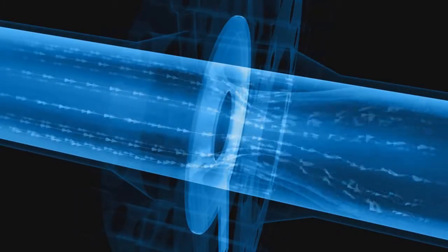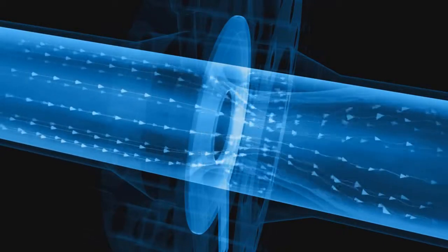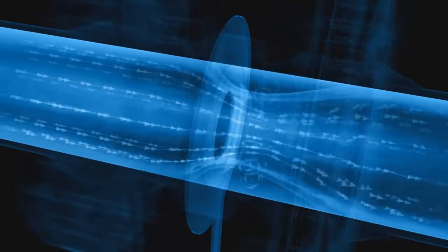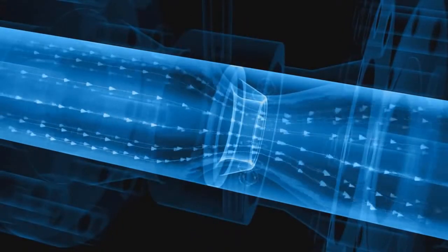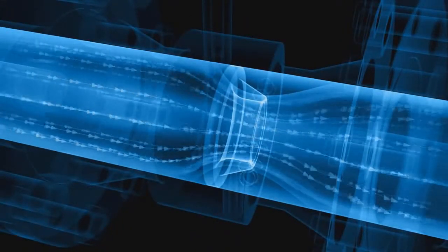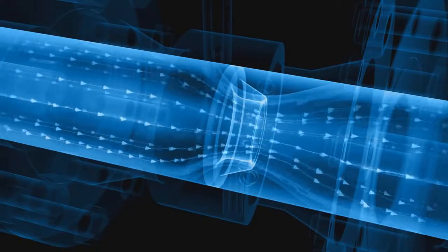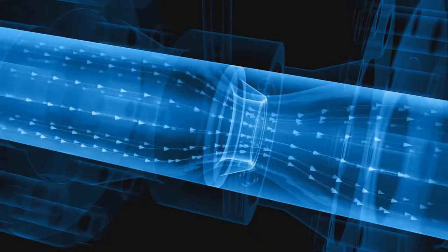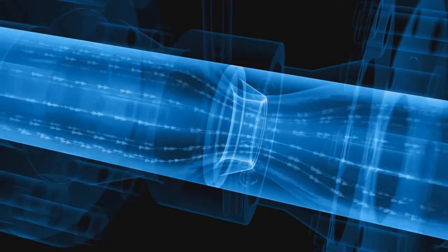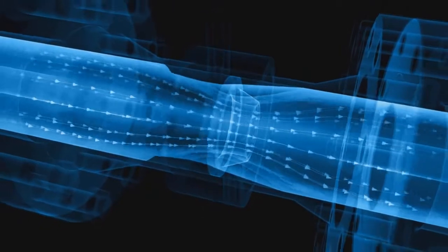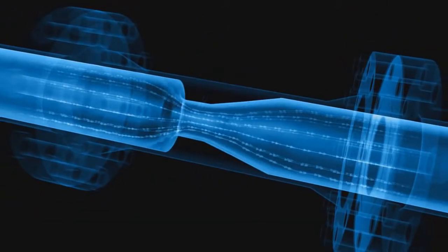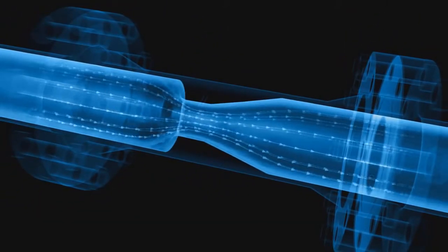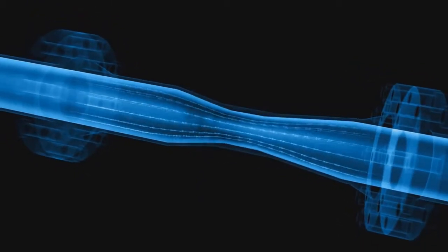This demonstration shows that an abrupt restriction generates severe turbulence in a fluid. Nozzles with a rounded, funnel-like inlet clearly reduce turbulence and thus create less pressure loss. Nozzles are particularly suitable to higher flow velocities or to fluids with abrasive solid particles. Turbulence reduction is even greater with Venturi nozzles, and finally with Venturi tubes, where the restriction is created by longer conical constrictions in the pipe wall.